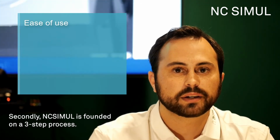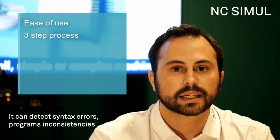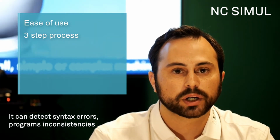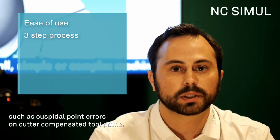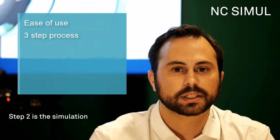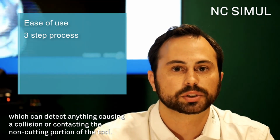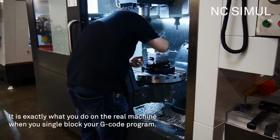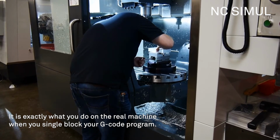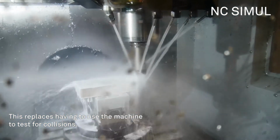Secondly, NC-Sim is founded on a 3-step process. Step 1, G-code decoding. It can detect syntax errors, programs inconsistencies, such as cuspidal point errors on cutter compensated toolpaths. Step 2 is the simulation, which can detect anything causing a collision or contacting the non-cutting portion of the tool. It is exactly what you do on the real machine when you single block your G-code program. This replaces having to use the machine to test for collisions.